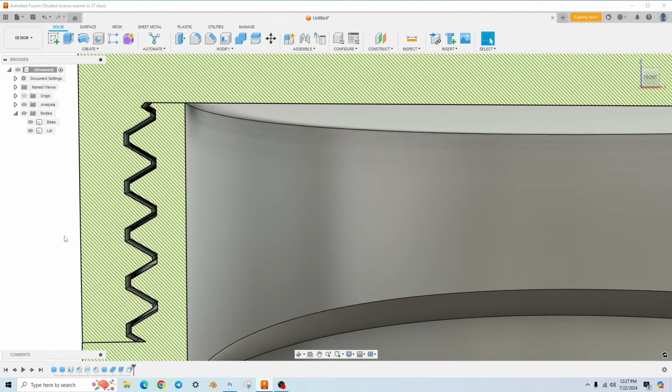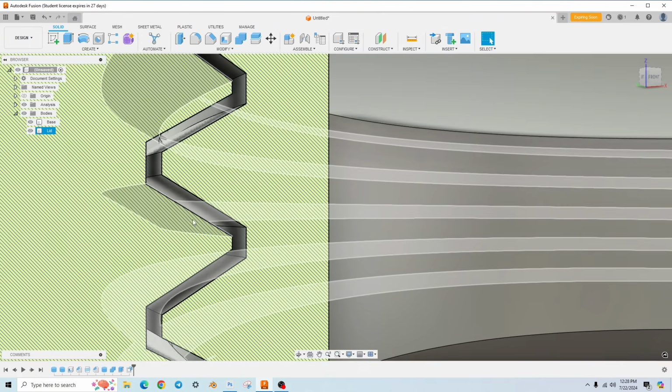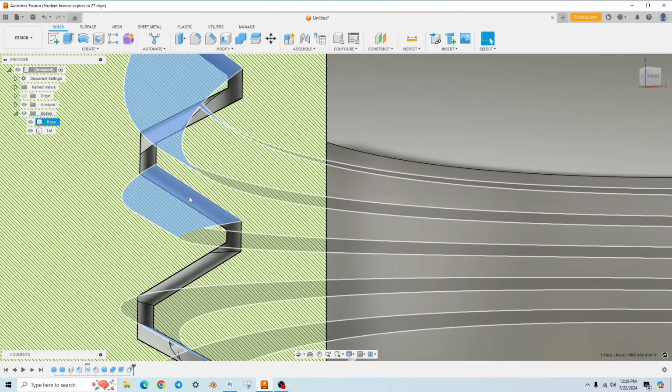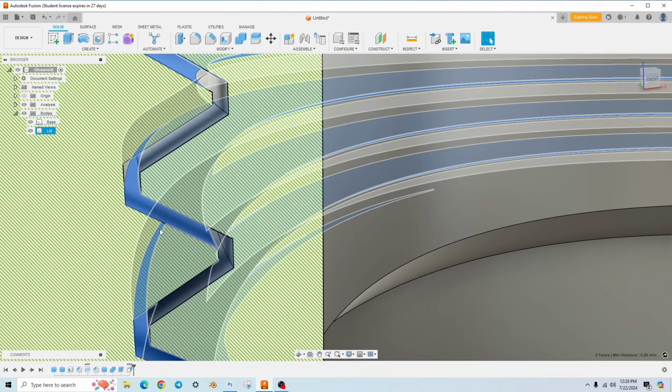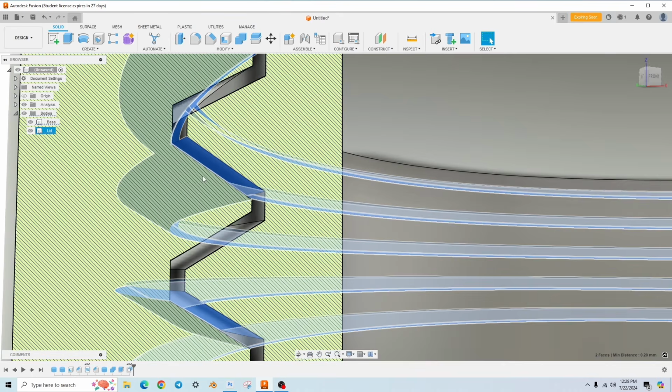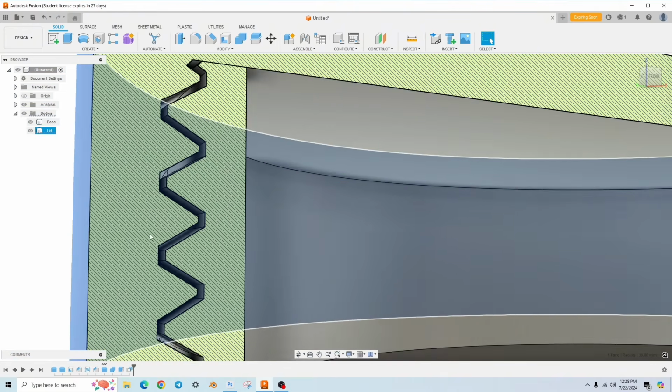Now before I was saying I was going to do kind of a combination between 0.2 and 0.3. And so we have created 0.2 millimeters here. And let me just make sure I did this right. Okay, so I shift clicked it and selected both faces. And if you go down here, the distance is 0.2 millimeters. So we did that correct.